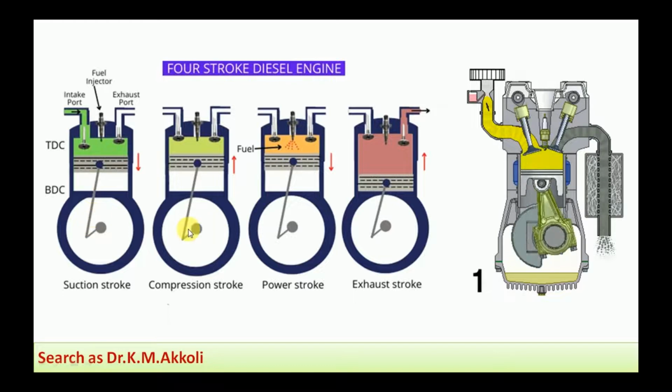The next one is the compression stroke. In this one the piston moves from the bottom dead center to the top dead center. Both the inlet and exhaust valves remain closed, and the air inside the engine cylinder is compressed to a higher pressure and temperature, and the crankshaft makes a half revolution in this stroke also.